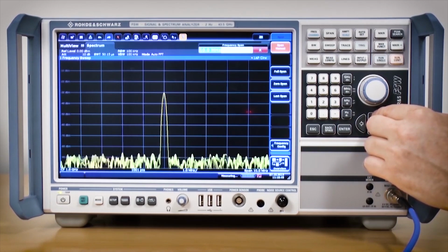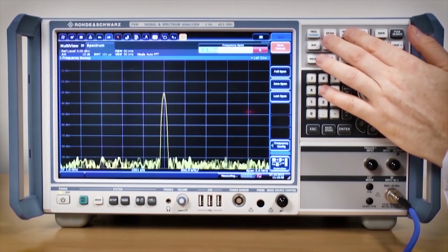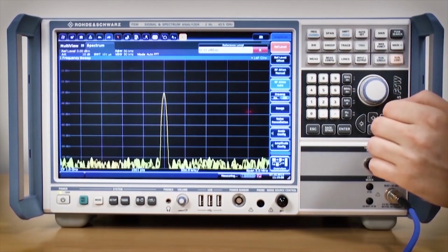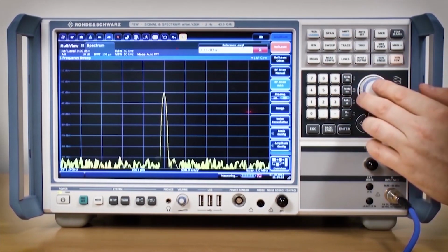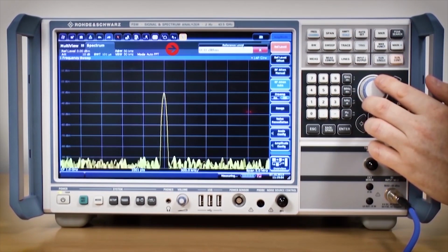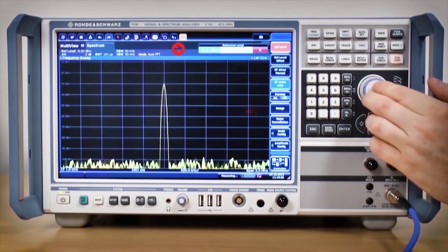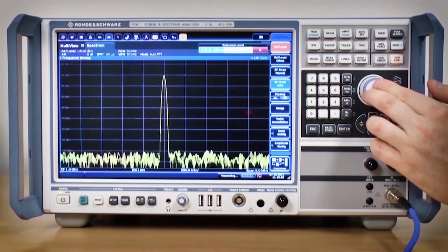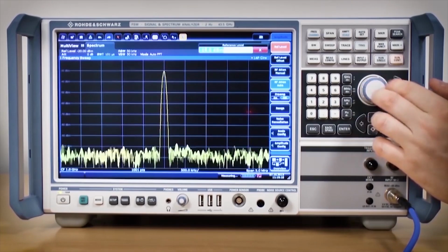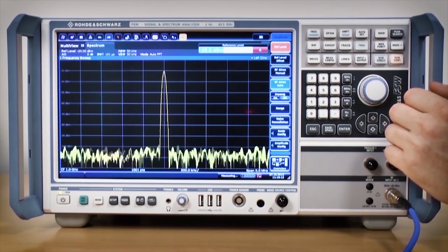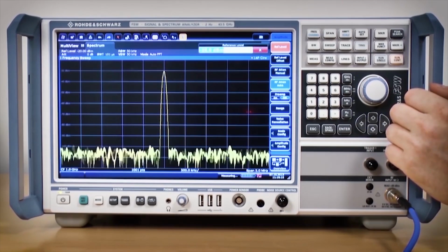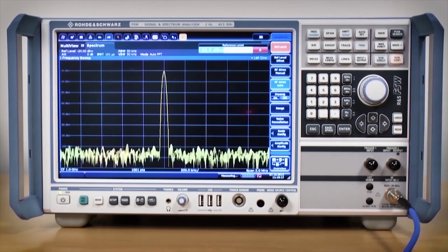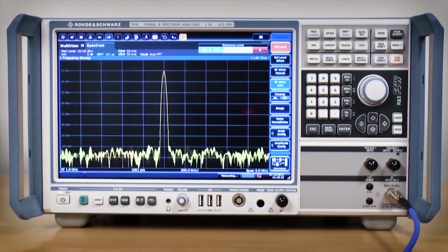It will usually be necessary to adjust the level controls. The reference level can be changed so that more of the signal of interest is seen on the display. Some older analyzers had separate controls for RF and IF gain. These days, modern analyzers combine the two intelligently, so that it's just a matter of adjusting the reference level to place the signal peak towards the top of the display as shown.